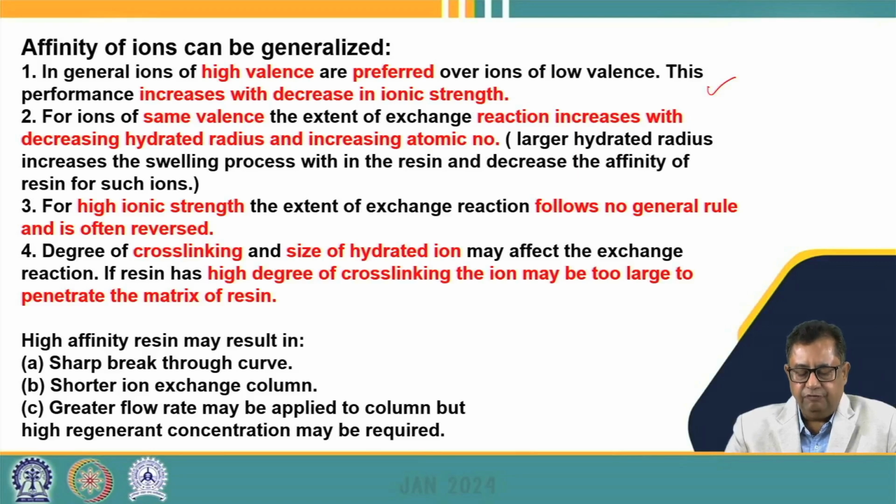Similarly, if we have ions of the same valency, the extent of the exchange will depend upon the hydrated radius. The lower the hydrated radius, the higher the affinity. Similarly, increasing atomic number increases the affinity. A larger hydrated radius increases the swelling of the resin, and that's why it decreases the affinity of the resins for such ions, because the pore size decreases as the swelling of the resin increases. So decreasing hydrated radius will always have a higher affinity towards the ion exchange resin.